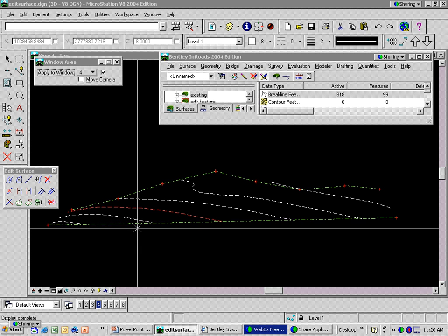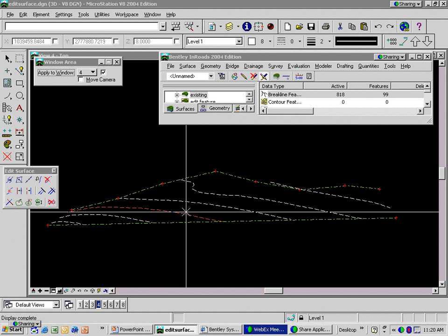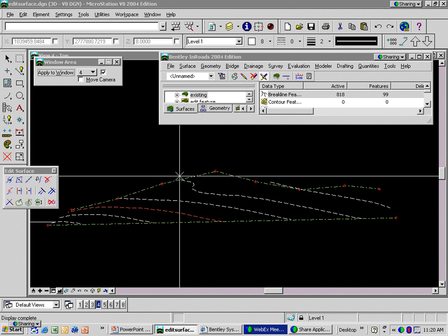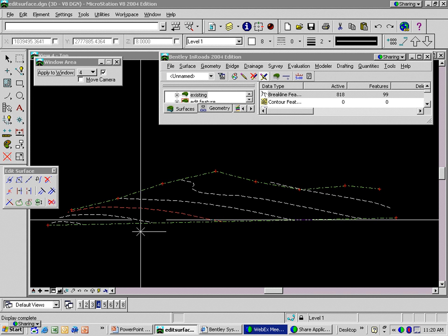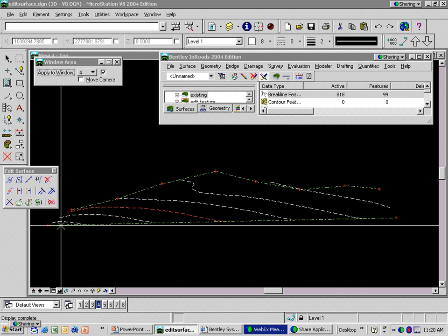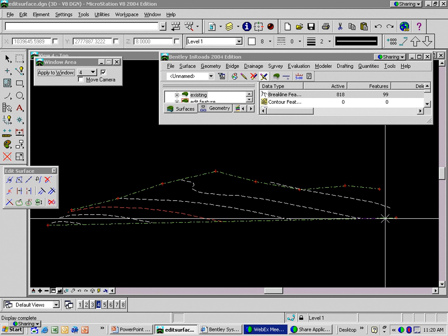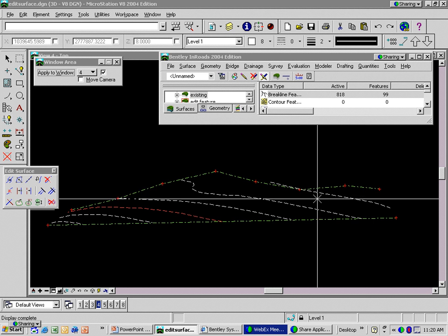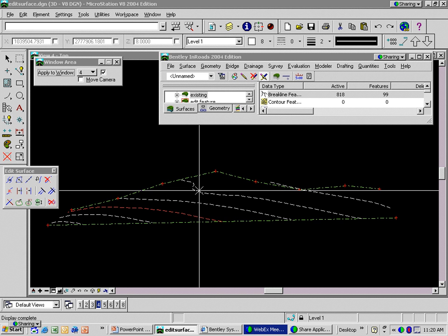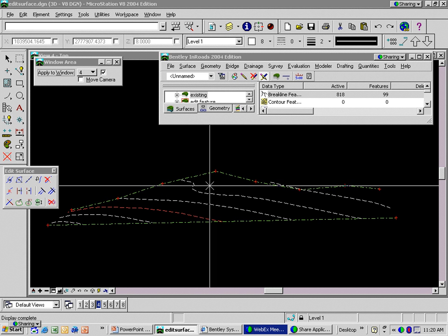Here's an example of a bank. Very simple. We didn't want to get anything too fancy with it. But bottom here we have a feature with 1 vertice point here, 1 vertice point on the other side. This feature has a lot of vertices defining it. As you can see, the contours in this section are doing things that would be pretty much undesirable.